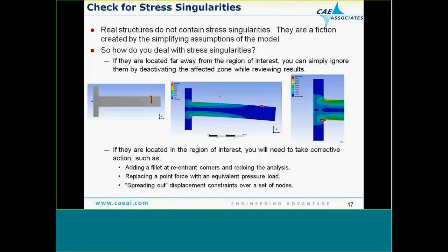Well, if they're located far away from the region of interest, so I have a point load applied here, but my region of interest is down here, I can ignore the fact that I get this peak stress right under that point load and simply select just this region for evaluating the stresses, and then I can see that I actually get the correct max stress for that region.